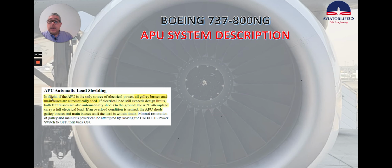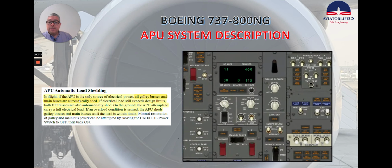Okay, APU automatic load shedding in flight. If the APU is the only source of electrical power, all galley buses and main buses are automatically shed. If electrical load still exceeds design limits, both IFE buses are also automatically shed.